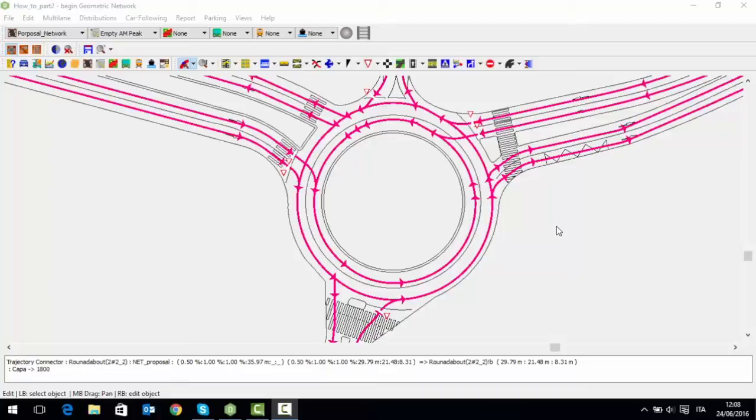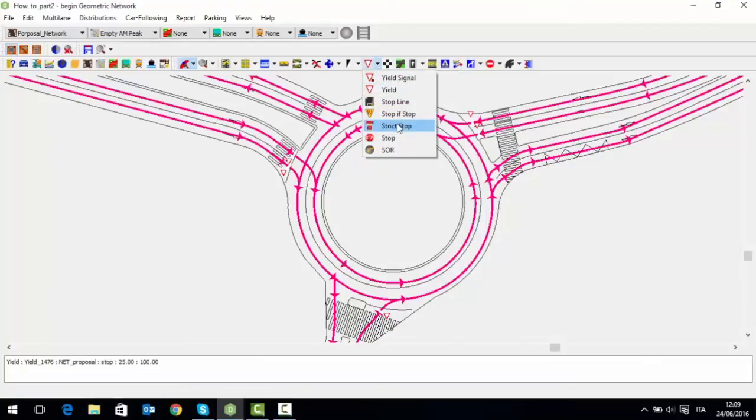We also need to manage the behavior of the vehicles that are already inside the roundabout. To do this, we need to use an additional element that is called strict stop. The first marker will stop vehicles into the roundabout when a vehicle is detected in the visibility area.